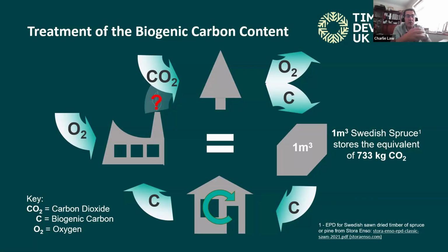There is obviously a question mark around that of the timber that we're producing now. Will that actually ever be released? We've got to talk about what we call bioenergy carbon capture and storage, or BECCS for short, where in 50, 60 years' time, when this piece of timber comes out of the building and it gets burnt in that type of plant, the carbon from that process, or CO2 from that process, will be captured permanently and stored somewhere else, whether that's in things like biochar or in underground caverns, whatever it might be. We might not emit it to atmosphere, but we're not allowed to take account of that process at the moment